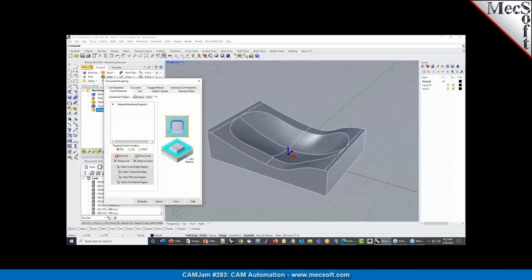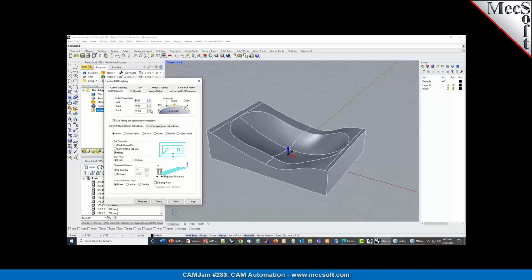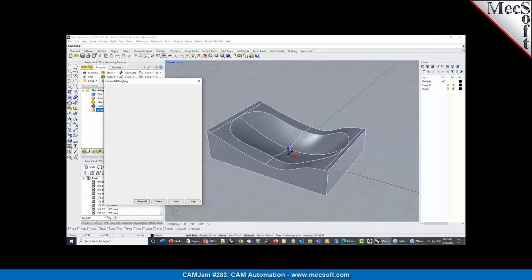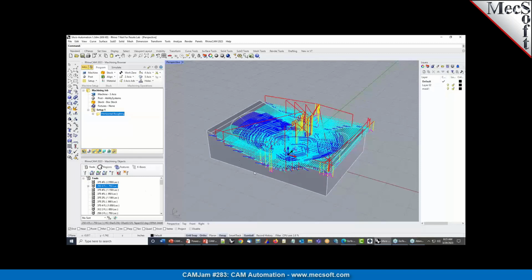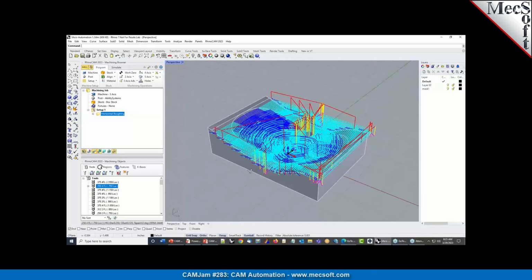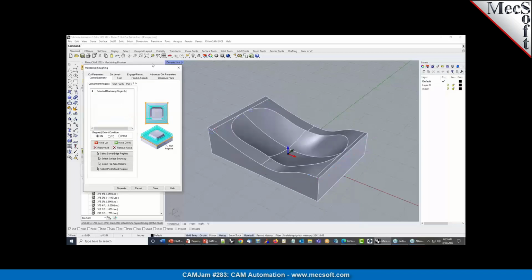Another thing I want to mention, we're going to get to talking about the defaults. Actually, I skipped that, and I'll talk about it here in just a moment. I mentioned that when you run the product or install the product for the first time, all of these parameters are set by default. So there's a value for everything. There's a value already defined for each of these tabs and each of the toolpath operations. So you can just go in and create an operation, pick generate without changing anything, and it'll calculate a toolpath and display it on the screen based on the default parameters that you have incorporated when you first install the product.